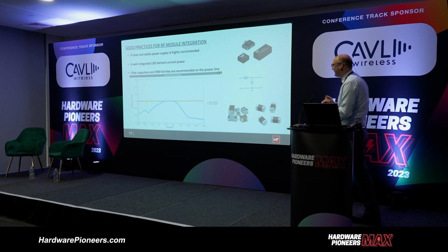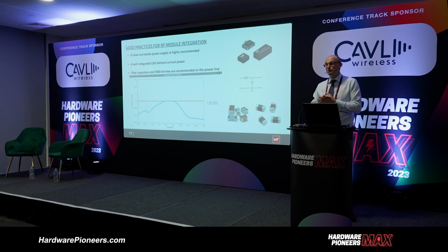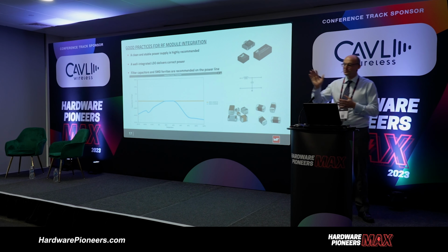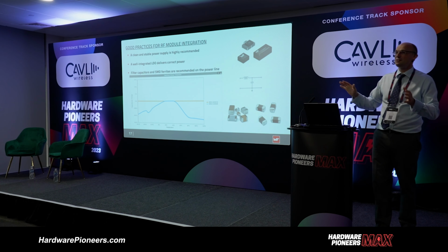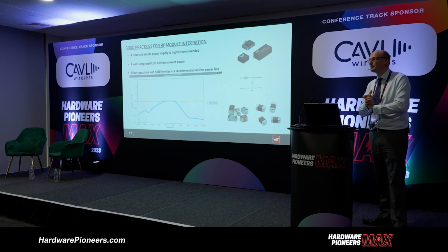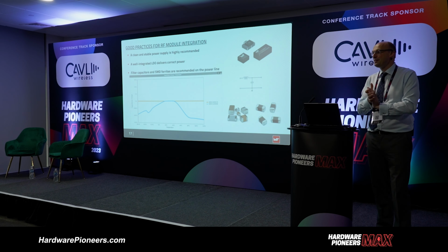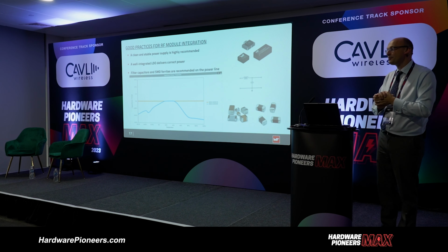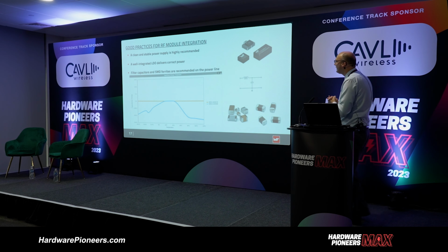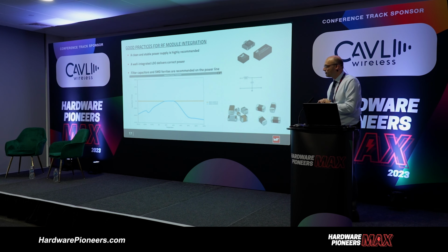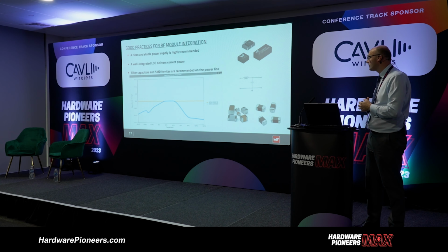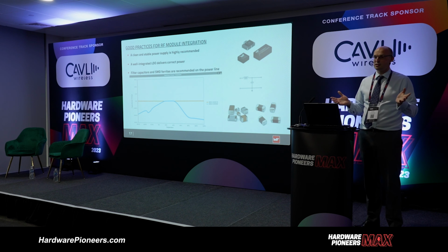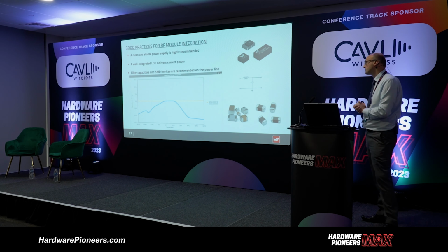Okay. How many of you take into account the temperature effect? If you take into account the temperature effect, nobody here is using X7Rs, X5Rs. You're paying the extra money in using MP0s. So I've got a few nods. Good. Okay. So once again, what you've got to bear in mind when you're talking about an RF module is that you want to make sure that any filtering that you're going to implement on that is going to be stable across that particular temperature range.